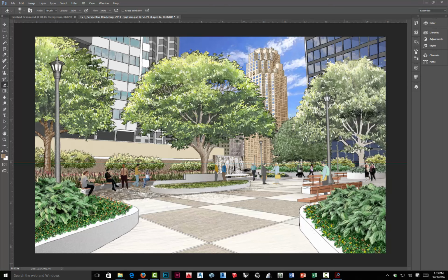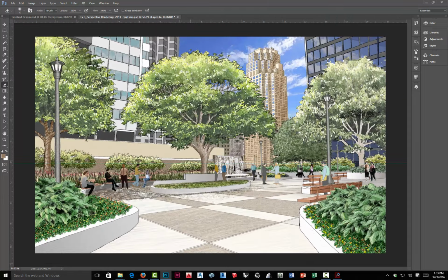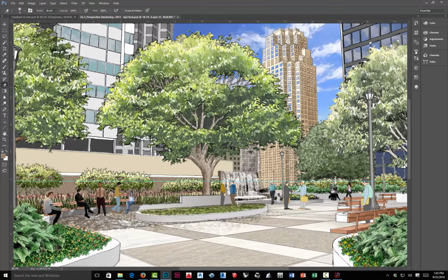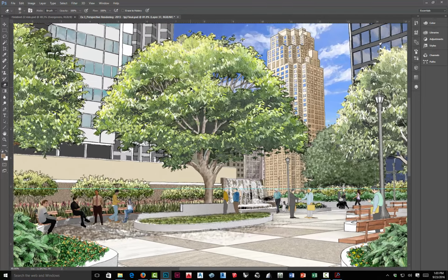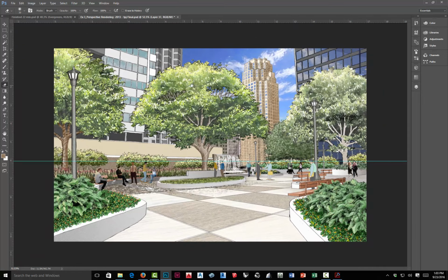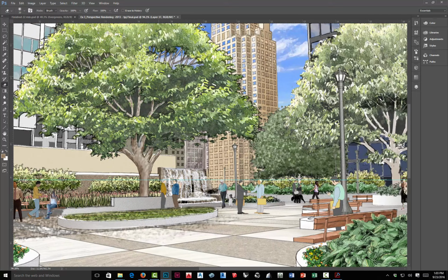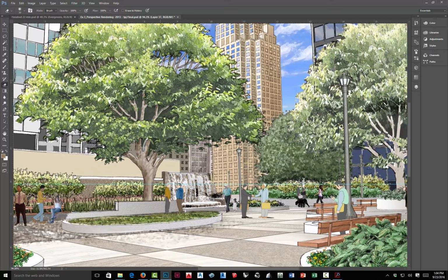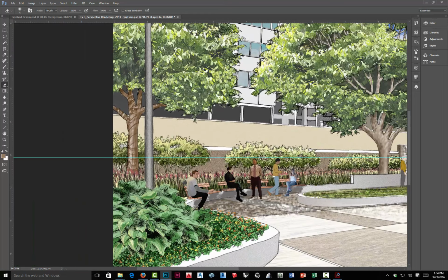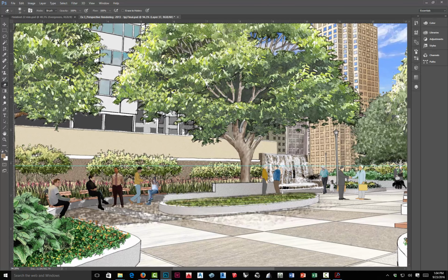The work area that you see here, I can zoom in and out. I actually have my preferences set so I can use the wheel of the mouse. On the Wacom tablets, we have either a slider or, mine has a little circle on it, that I can zoom in and out with. If I hold the space bar down, let me zoom in a little bit. If I hold the space bar down, I get the pan tool, and we usually set the pen so that the upper button activates the pan tool. So if you're zoomed in to see detail, you can still move around easily, but the space bar will activate it as well if you have another tool actively in use, like the paintbrush or the eraser.